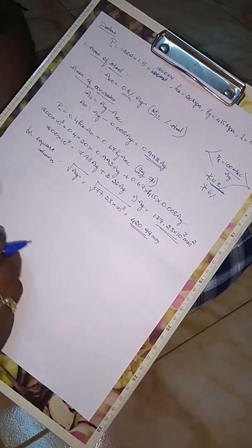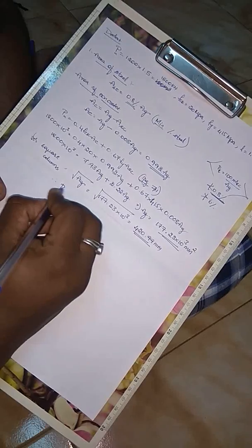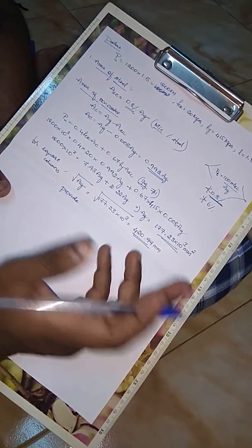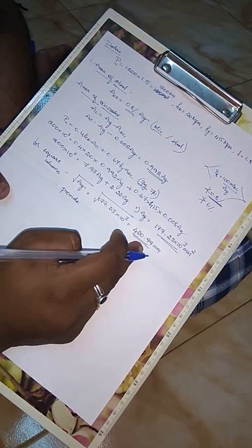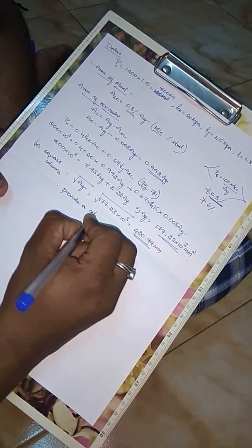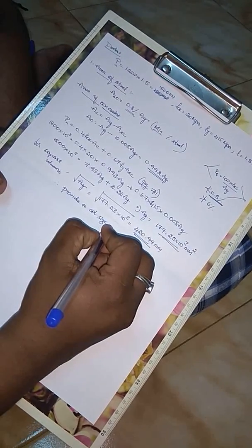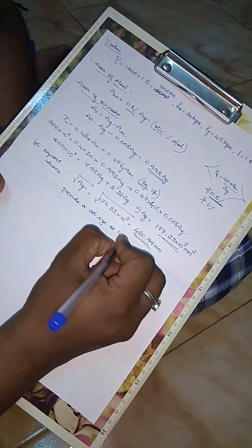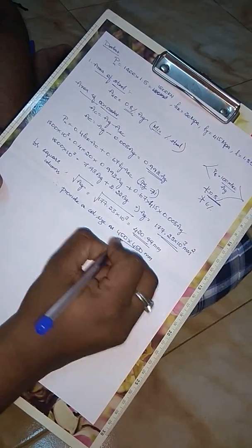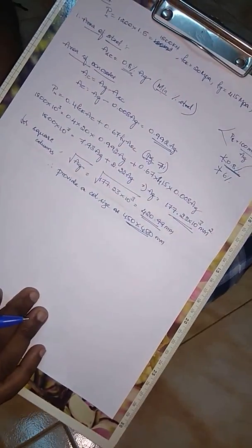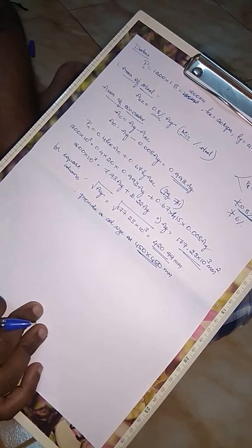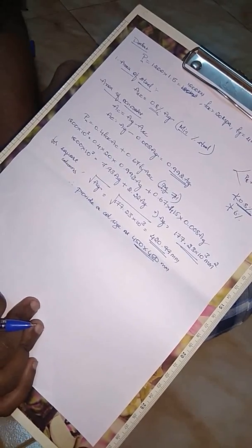So don't take 420 or anything less than the value you got; you can take a higher value. Provide a column size as 450 by 450.